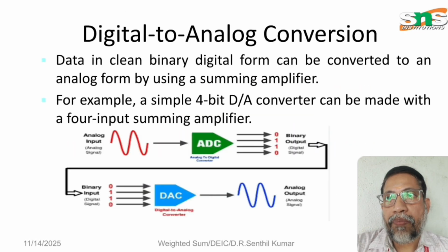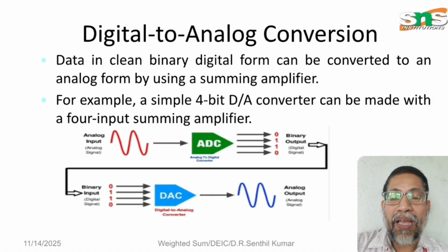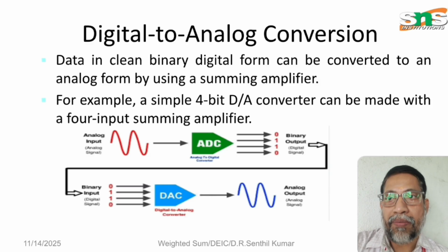Yes, this is digital to analog conversion. Data in a clean binary digital form is easily converted into analog with the help of a summing amplifier, an operational amplifier acting as a summer.